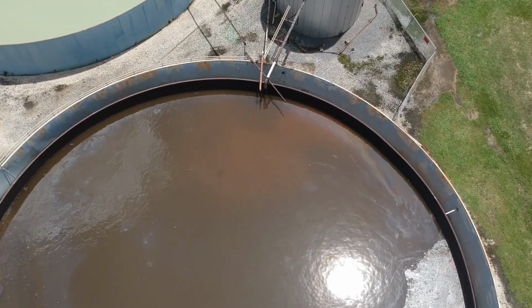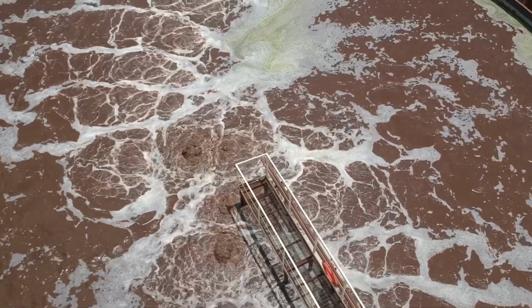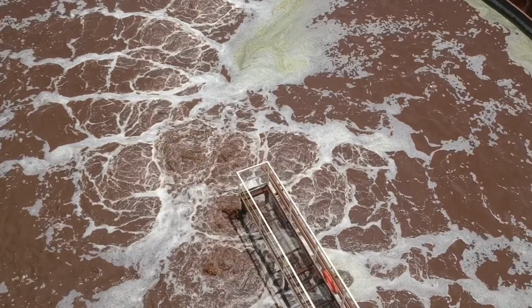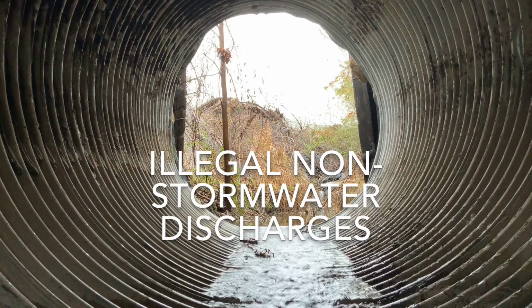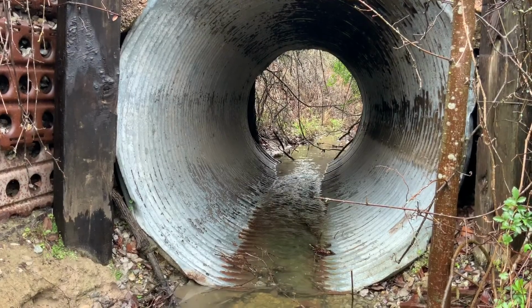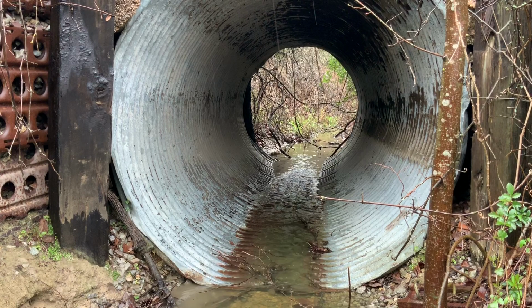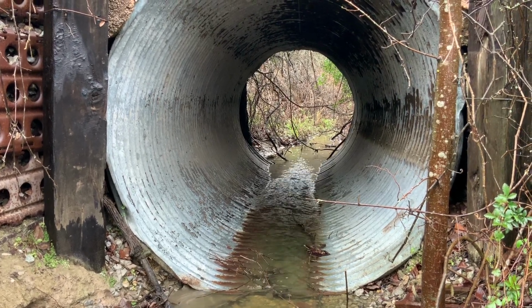It is important to understand the difference between stormwater and wastewater. Stormwater can freely flow from the plant. However, wastewater should always stay contained inside the wastewater system. Non-stormwater discharges are illegal. These include washing down spills, leaks, wastewater, and other industrial chemicals into a storm drain, ditch, or outfall. Non-compliance with stormwater regulations can result in fines as high as $27,500 per day.